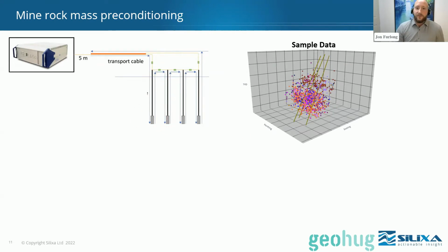These were 25 to 30 degree dipped boreholes. So the fiber goes down and then it comes back up. We fusion splice it at the surface and it goes down and comes back up, kind of just like the New Afton example from the beginning. And then we interrogate it all with one interrogator. In this example, they injected for a couple of days to precondition the rock mass, and we detected a total of 5,000 events.